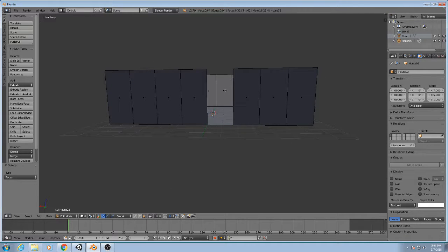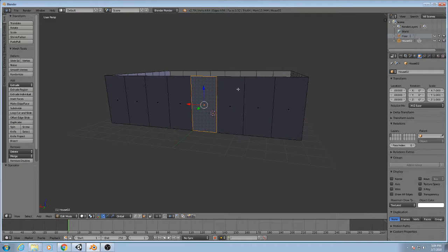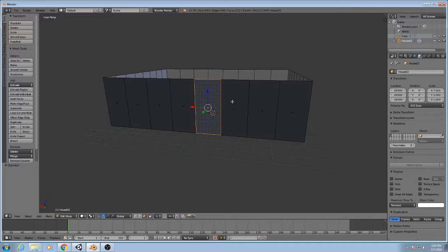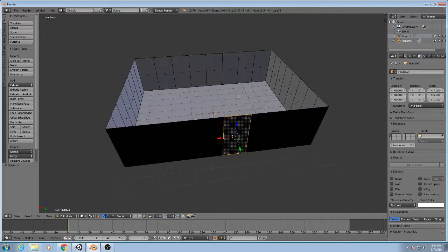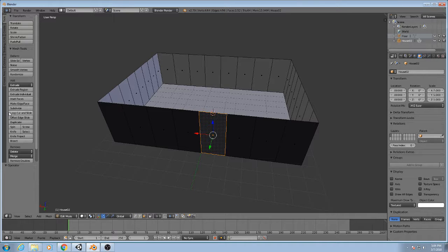So how are we gonna make a door that's this high, and probably just the width of this box here? Well, we have to be in edit mode, and we go to the tools, loop cut and slide. Click on this and go onto the object you're working on.